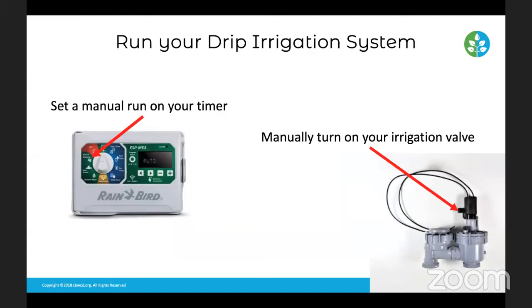Small tears, you might hear a little hiss. It's not always a catastrophic break of the tubing and a puddle forming. So it's very much a look, listen, and feel around when you have drip irrigation, especially if it's either subsurface under the soil level or just covered and topped with mulch.